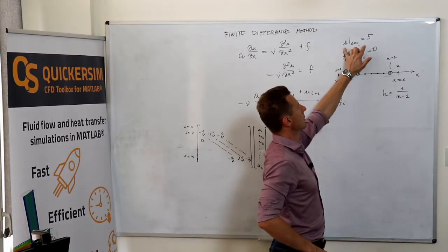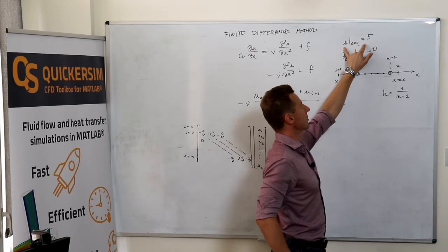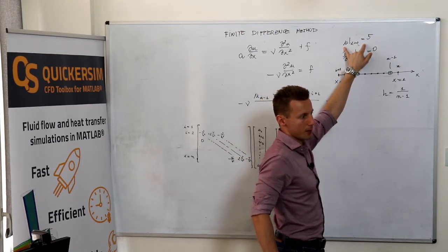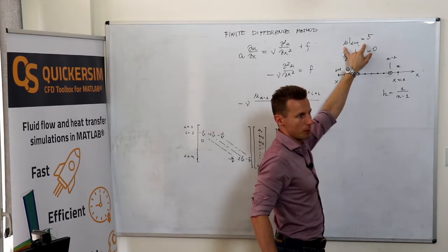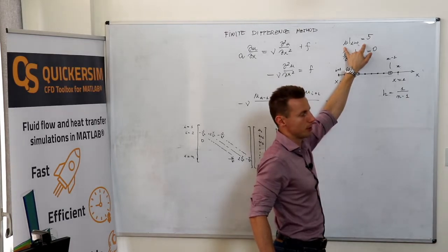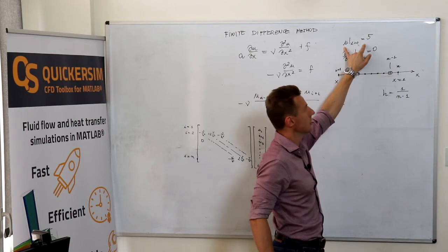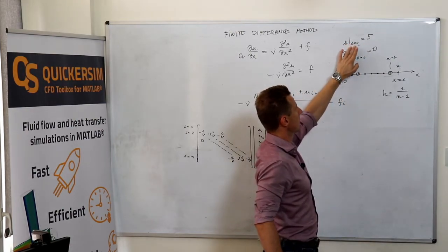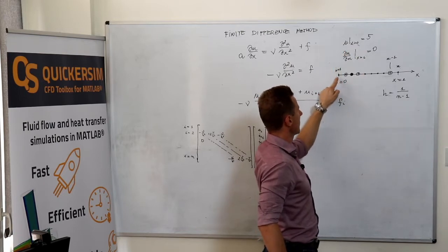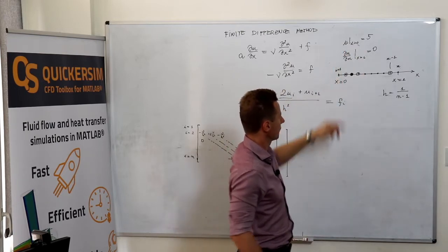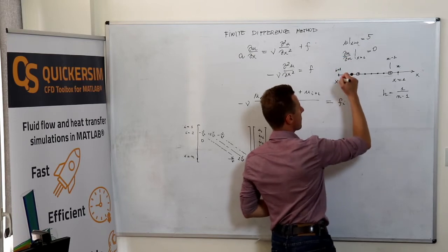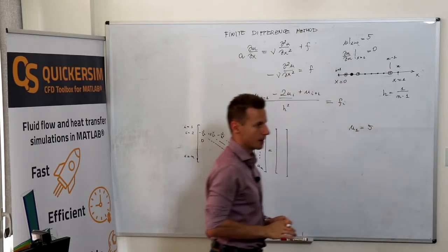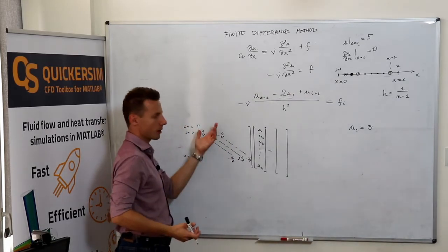What we need to do is, we already have an algebraic equation, so there is nothing to discretize. We just need to impose that boundary condition. So basically we need to introduce this equation to the matrix. And we see u at x equals 0, so basically u1 equals 5, and we need to introduce such an equation to our matrix.